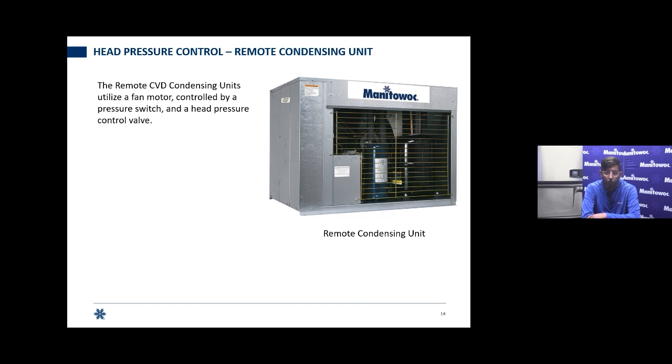All right, but the CVD systems, a little bit different there. We have a fan motor, but we also have a pressure switch to call for that fan motor. So the same way you would diagnose a pressure switch on the self-contained air-cooled, the same principle is going to be here. And we have a head pressure control valve to maintain head pressure. So we want to bypass that condenser and keep the receiver downstairs at an acceptable temperature.